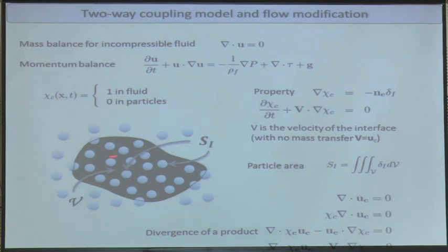The way to do that is to do the same momentum and mass balance derivation for the equations, but including the effect of the particles. It can be done by averaging techniques, where you have many particles in the domain, and you make a mass and momentum balance on the fluid containing some particles.